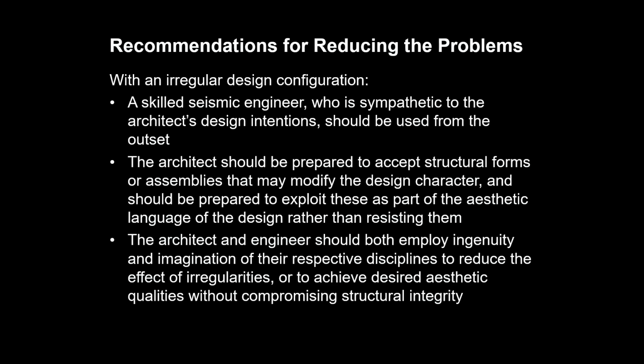And he has noted a skilled seismic engineer who is sympathetic to the architect's design intentions should be used from the outset. And the architect, and this is most important to us, should be prepared to accept structural forms or assemblies that may modify the design character, and should be prepared to exploit these as part of the aesthetic language and the design rather than resisting them. The architect and engineer should both employ the ingenuity and imagination of their respective disciplines to reduce the effect of irregularities or to achieve desired aesthetic qualities without compromising structural integrity.